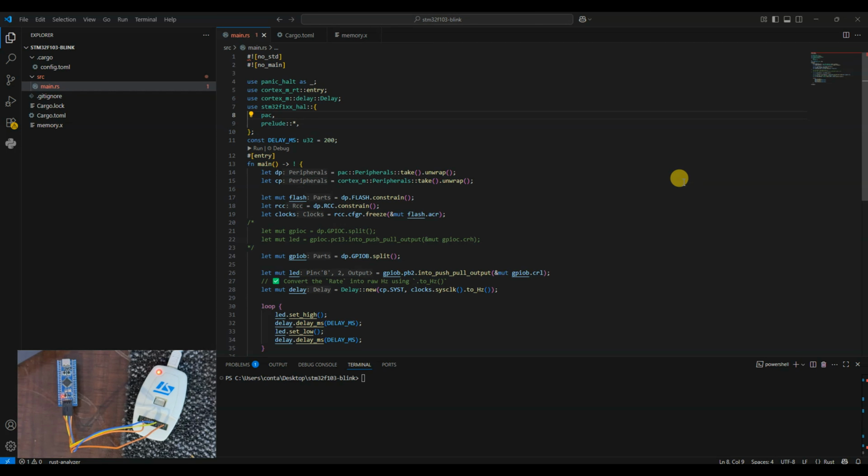In device peripherals we have peripherals like GPIO, UART, etc. And in core peripherals we have peripherals like NVIC, system timer, like that. This PAC, or peripheral access crate, is generated from the System View Description file, and it provides direct access to all microcontroller peripherals.